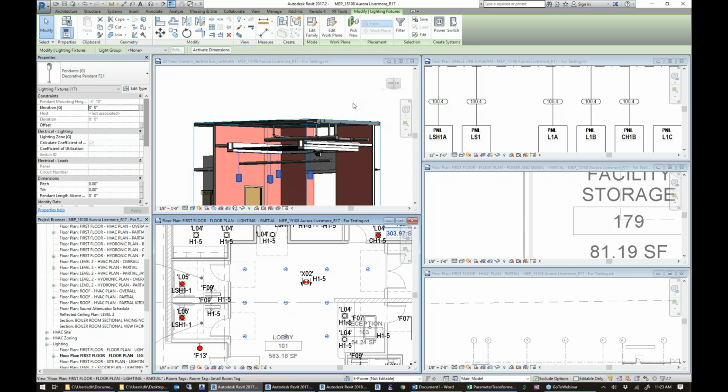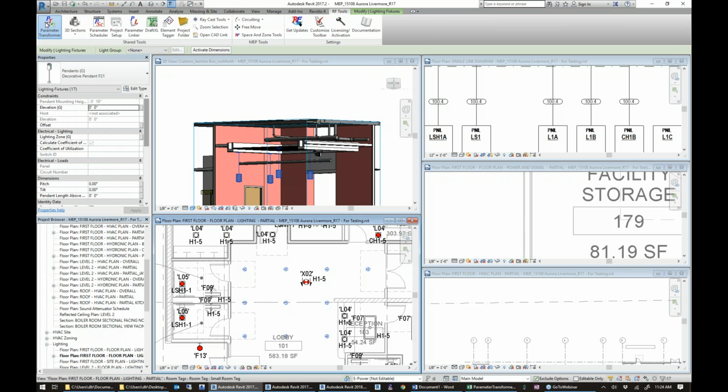We talked about linear things. All of these tools that I've discussed will work with linked models, meaning you can filter for linked data. You could filter for linked rooms, linked plumbing equipment. You can say for all toilet fixtures in the linked model, I want to create this type of connector or something in my current one, or gather electrical information from a linked model and transfer it to electrical fixtures in this model, or whatever. So lots of different use cases for that, and many that I probably haven't even thought of.